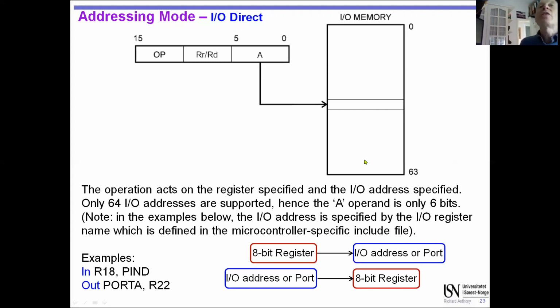So these special registers, such as the ones we've already looked at, PORT A, PIN A, data direction A, are all examples, and you see some here. These have their own special address space. So when you're talking about PIN D in your code, in assembly or embedded C, it allows you to do things at a lower level.